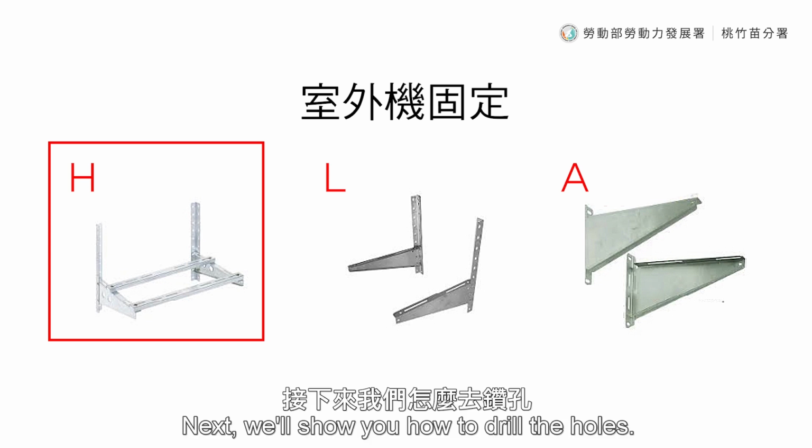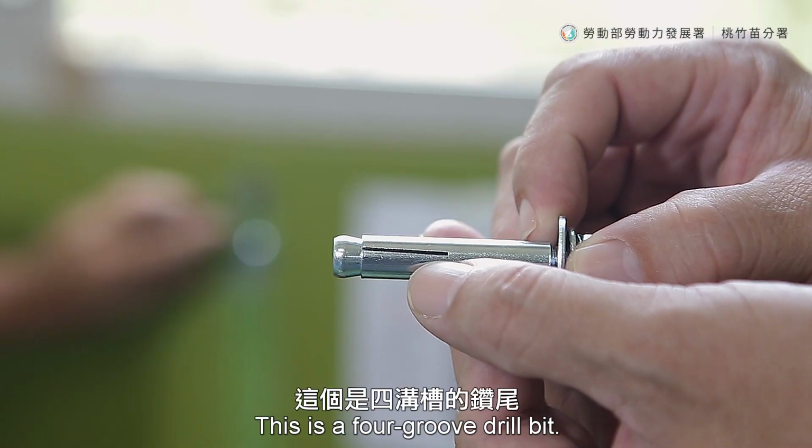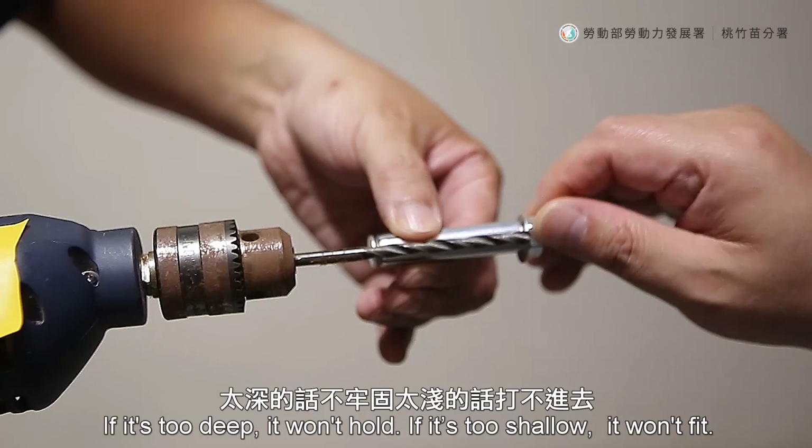Next, we'll show you how to drill the holes. This is an expansion bolt. Sometimes we call it a gecko. This is a 4-groove drill bit. As you can see, this shows how deep you should drill. This is crucial. If it's too deep, it won't hold. If it's too shallow, it won't fit.